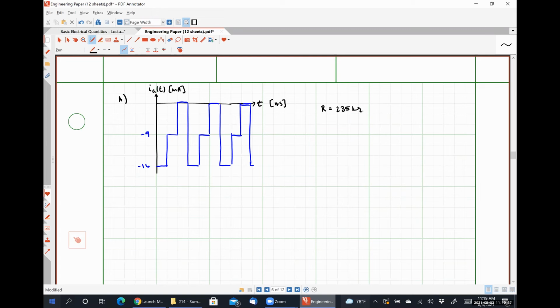Then you need to find what the period is, big T. Okay, so that is definitely going to be one portion of it. So what do you believe the period to be? So let me be clear. This is 1, 2, 3, 4, 5, 6, 7, 8, 9. 3 milliseconds. All right, so you're measuring from here to here. That's big T. And that is exactly 3 milliseconds. Okay, so that's a great start.